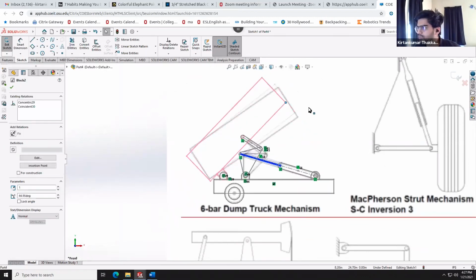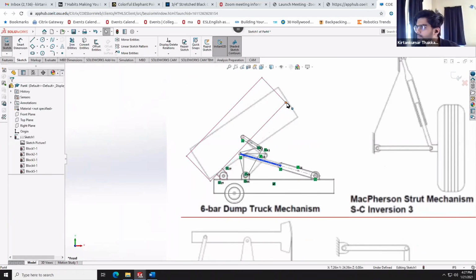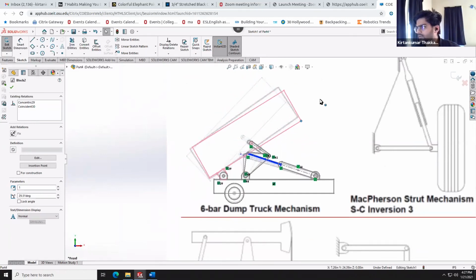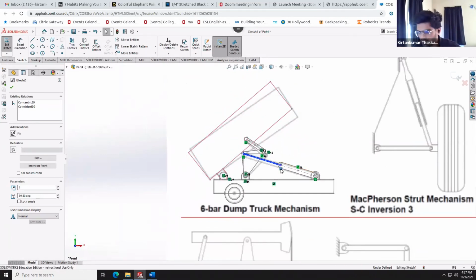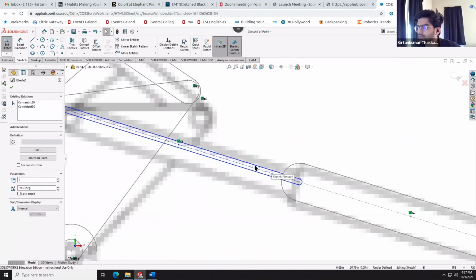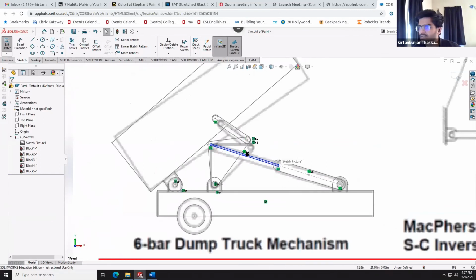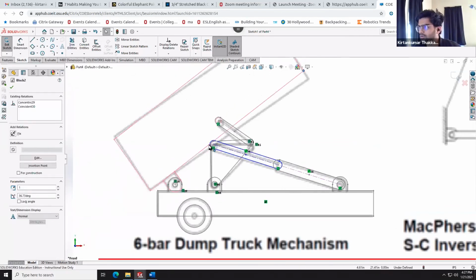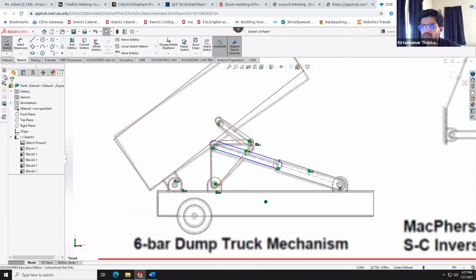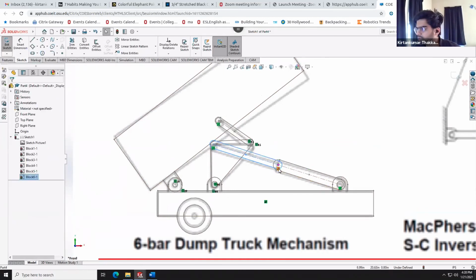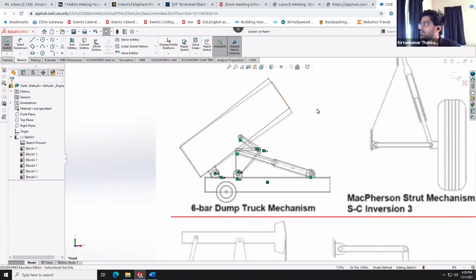Okay. So you can pretty much see, although this is coincident, that's why it is not moving. I'll delete the coincident constraint over here. And the other thing is I actually forgot to make a block, so that's why it is changing the dimension. If you make the block over there, this is good learning. Okay, so I'll make a block. Over here we have the block and done. However, I would delete this coincident feature. And now I think we are ready.